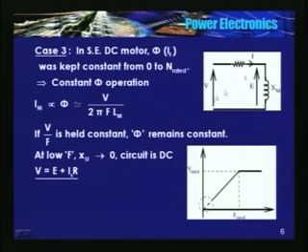But if I am adding the magnitudes directly, it may so happen that there will be a significant difference in the magnitude of E and V. Now see, E is V minus Is into R, direct magnitude subtraction.